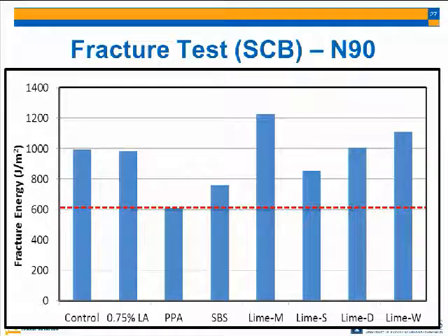So what happens is when you put it with asphalt and cool it down, this moisture is going to start coming back to the surface of the aggregate, right? And with the pressure from loading tires, or if you also still have water in the voids and so on, it's not a very simple mechanism. That makes sense from a stripping perspective. Of course. Are you saying warm mix is not a good idea?